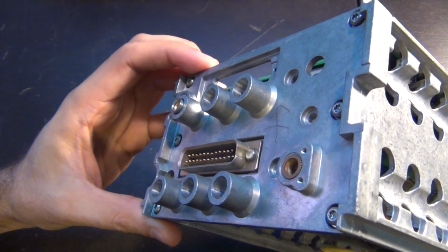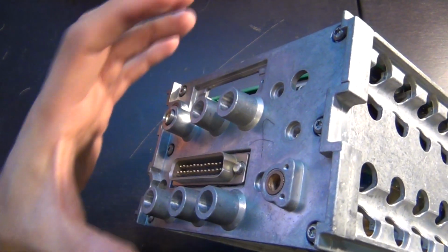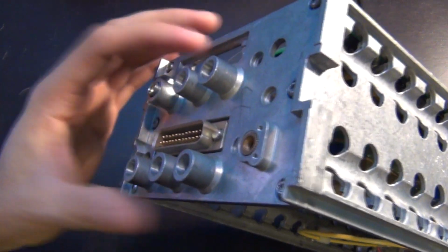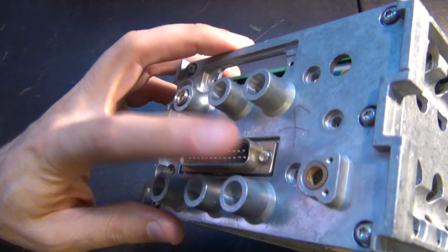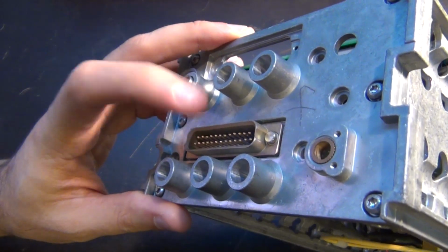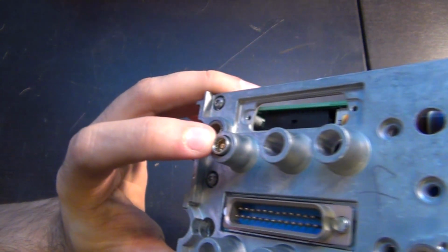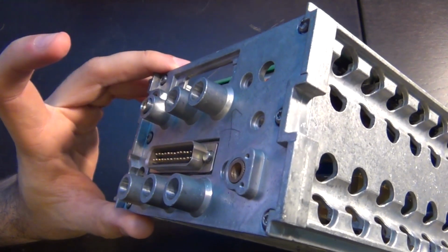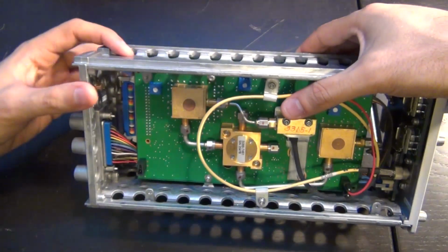And at the back here is the interface to the DCA mainframe itself. And you can see that there are many empty connectors here. That's because this chassis is for all the different modules. So depending on the module, this will be populated differently. In this case, there isn't really much to send back to the oscilloscope. There is a parallel interface for power and low frequency stuff, and there is one analog RF interface, which is a coax cable that gets plugged into the back of the DCA, and I'm not going to tell you what that is yet, so you can think about it as we go forward. But since you know the architecture, you should be able to guess what that is for.